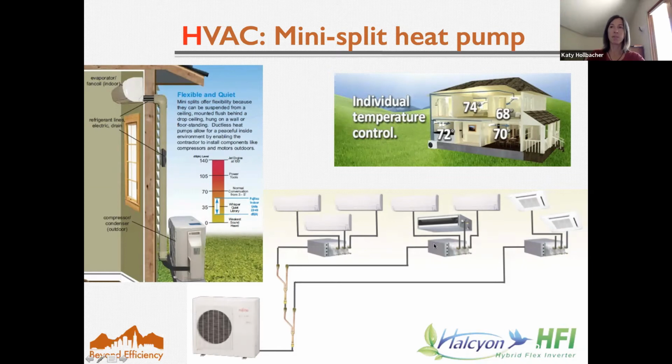This is just one of the many systems available. This is Fujitsu. We tend to actually use Mitsubishi more, but you have an outdoor unit that then feeds various indoor units. This could go in a living room. Maybe you have a separate one in each bedroom. You can have ducted, recessed indoor ducted fan coils that would then have short ducts into spaces if you don't want this unit hanging. And then there are also these ceiling units. This is pretty typical of these mini split systems.